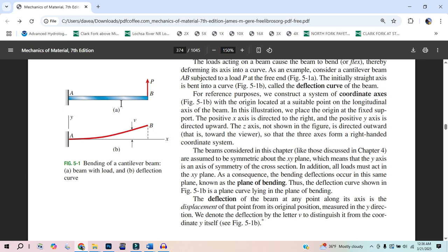So if we're saying a downward force on the right is positive in the vertical direction, which is what we're doing, we're cutting this thing and trying to find the internal reaction, and the shear force is always going to be on that cut in the vertical direction. But when we take a little chunk of that, we're going to have a vertical force. Downward is positive on this side. Upwards is positive on that side. That's going to cause this thing to rotate that way. And if it's in pure shear, we have to have two opposing forces, one this way and then one this way.